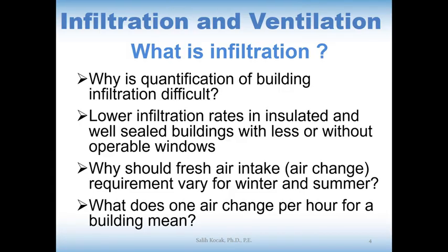9 times 12 times 8, this is gonna be the value, times 1.5, which is the air change per hour, divided by 60. Why are we dividing by 60? Because 60 minutes per hour. So the result is gonna be 21.6. This is the CFM value.